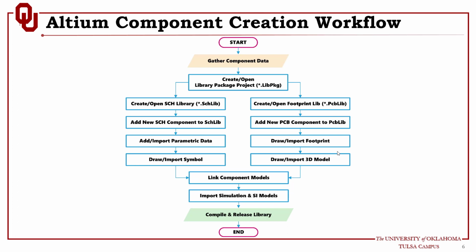But be aware that if this component is not from the manufacturer part search or from Altium content, be careful before you use it. You need to do a check. You need to make sure that the pins of the symbols are correct, the mapping between the schematic symbols and footprints is correct, and the spacing on the footprints is according to the IPC standard, and so on.